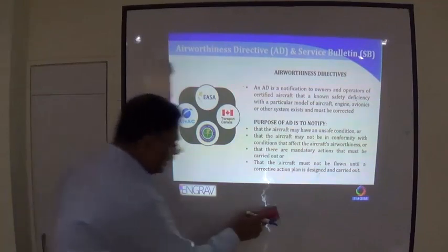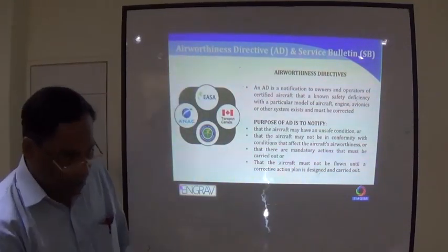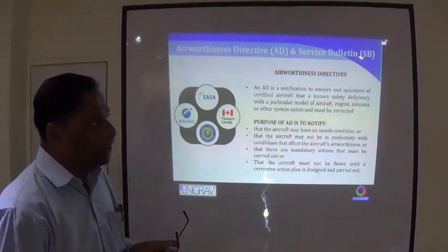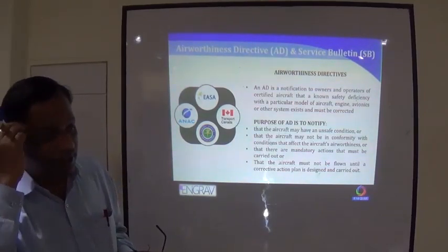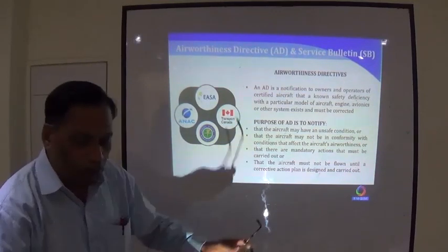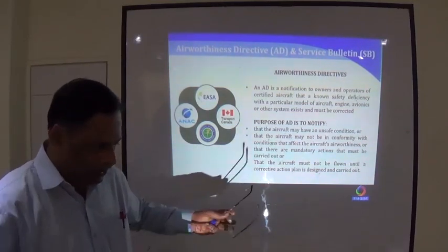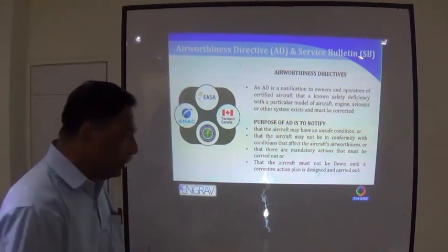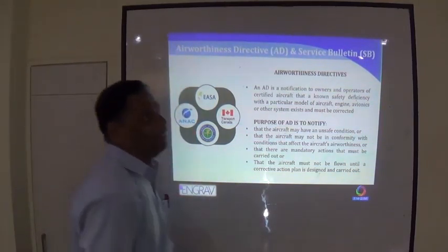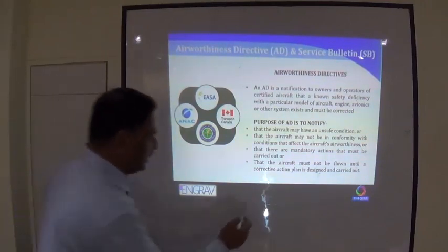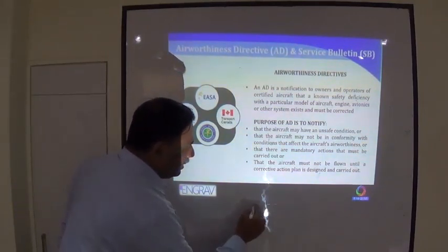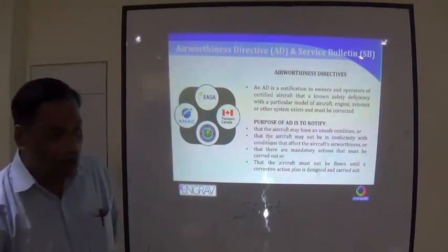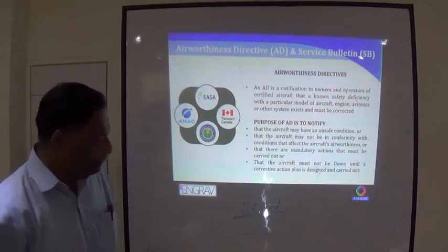It's an engine officer's job, based on the fuel in each tank. And in the ships you have something called a ballast tank, where you put seawater. You take seawater from the sea, and that's for ensuring the stability. Then fuel: when we used to sail, we used to carry almost 80 kL of diesel, 80,000 liters of diesel in the fuel tank.